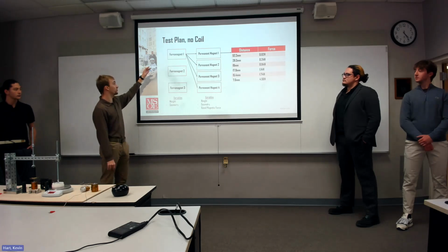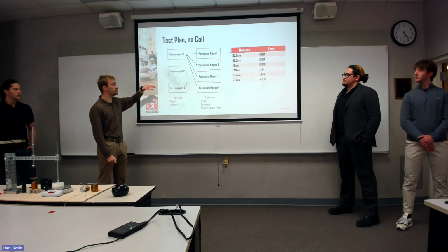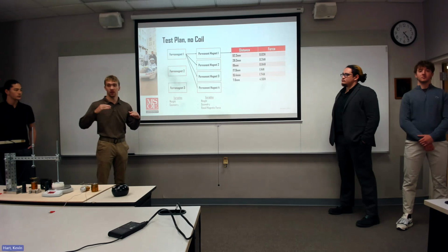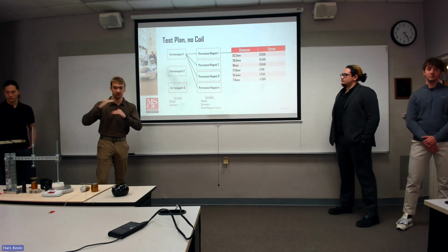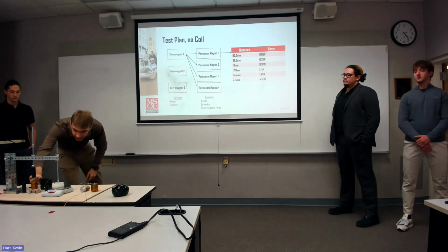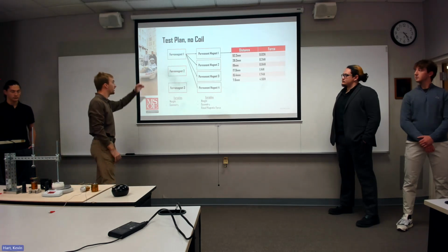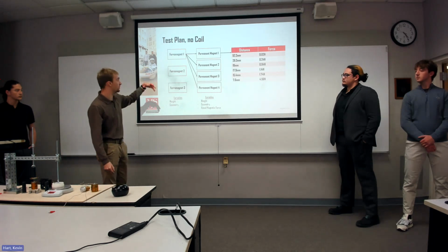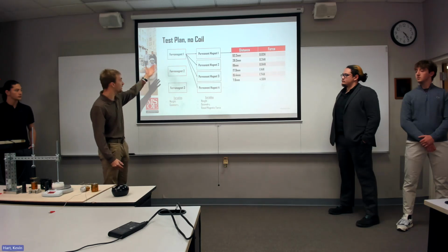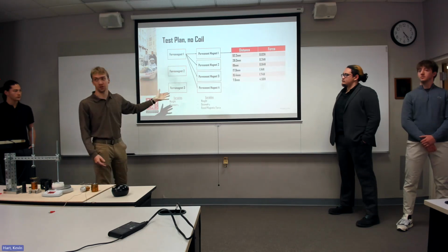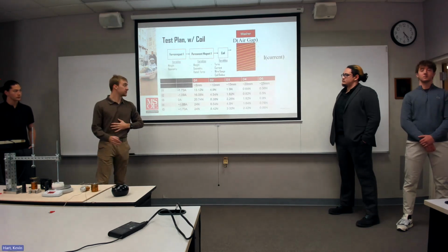And what we would be doing is we pair these different magnets up and essentially see how the force changes as we get closer and closer between the washer and the magnet, right? So this is our air gap distance. That's what we were varying. And then the force is what we were recording. And we did that with our first ferromagnet, changed the different permanent magnets, and then reiterated that same process with each other washer.